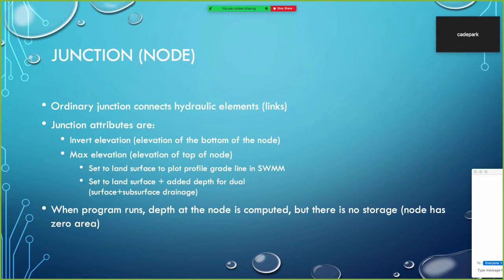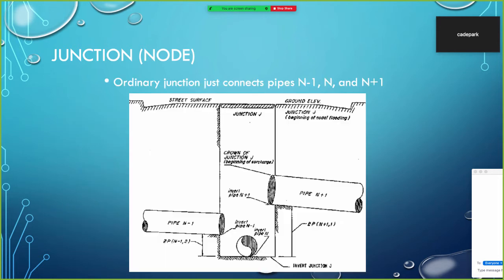And so if we have flooding losses in the output report, we've run a simulation for a case where our drainage system isn't working as designed. And that's actually desirable for us, because we can use that to locate where that flooding occurs and then implement design changes, retest our design in the model until we can contain the design discharges completely in our planned drainage network.